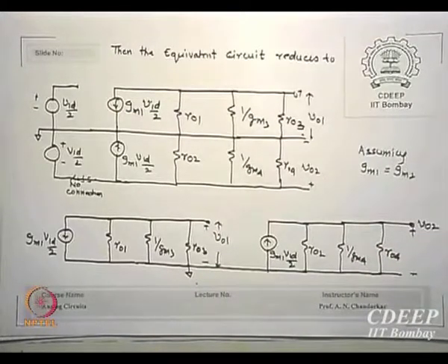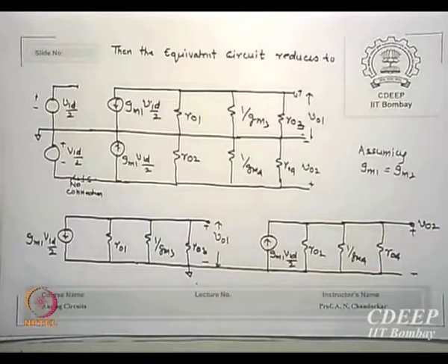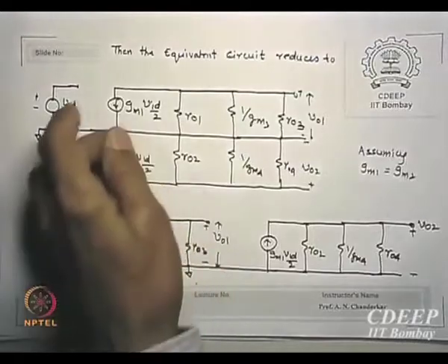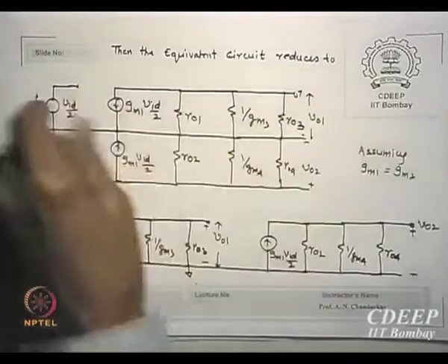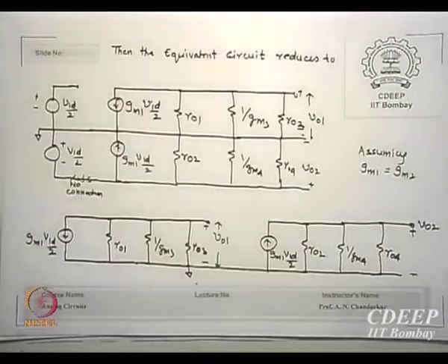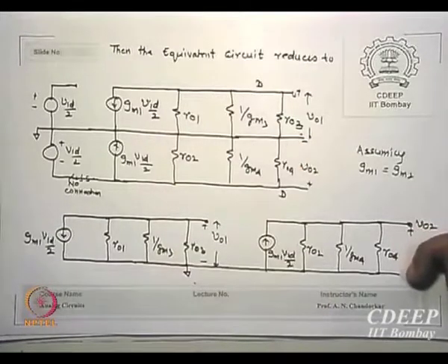Do you see two circuits? Actually they need not have been drawn one over the other. This is an independent circuit and this is an independent circuit, and in between there is a ground. Just to save space, I showed you one ground, the opposite one. Is that clear? These are two independent circuits. Is that correct? The VO1 and VO2 are independently seen by us. Since the source is common, I am using a common line here, one on this side and one on the other side. So this is drain, this is drain. Please remember these are the drains of both the transistors, the outputs of M1 and M2.